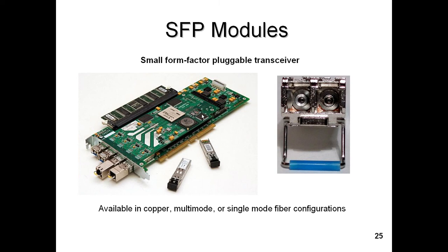Now, one of the interesting technologies that's coming out are these SFP, or small form factor pluggable transceivers. These are devices that can be plugged into circuit boards that provide different copper, multimode, or single mode connector configurations, and you can change them around. So it makes it quite attractive for manufacturers so that they can simplify their process. If a customer says, I want this to be a multi-mode transmitter, hey, no problem, we'll plug these modules in. Oh, we want this to be a single mode transmitter or receiver. Hey, no problem, we'll plug that in for you. So that's one of the innovations that's happening in the fiber optic business.